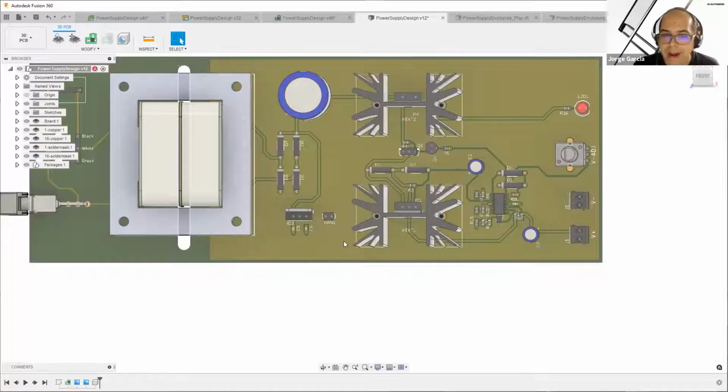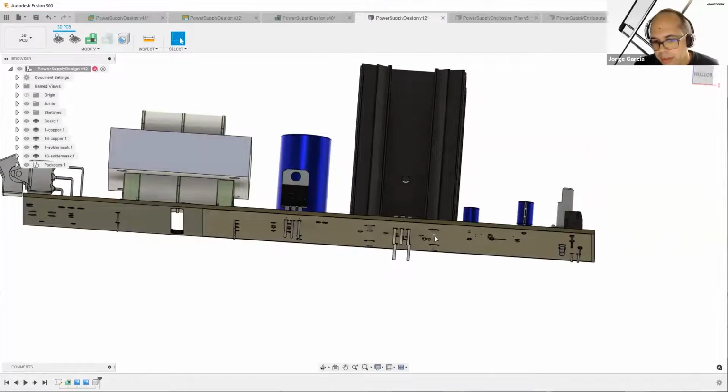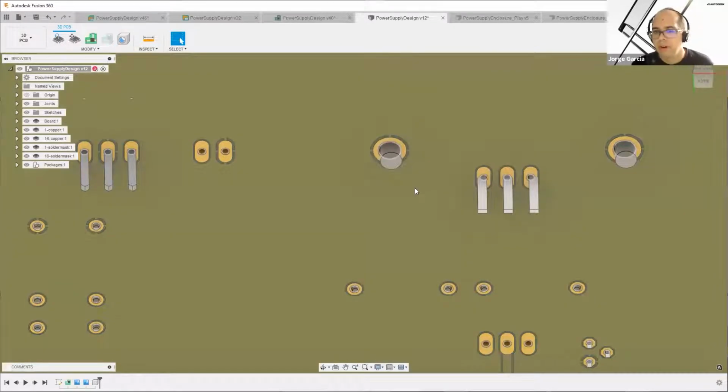As designed right now, when I bought these heat sinks, they actually have these little nubs, and those little nubs solder into the PCB. Okay. So if you look, they have some thermal relief. They're set up to solder to ground. While they do have thermal relief on the pad, let's remember these are heat sinks, and their job is to transmit heat away. So while it is perfectly possible for us to solder those, it does create some challenges in the amount of heat we have to apply to get those up to the temperature they're going to need to be. And this is the sort of expertise you gain when you've done a few thousand of these. You start to see these patterns.